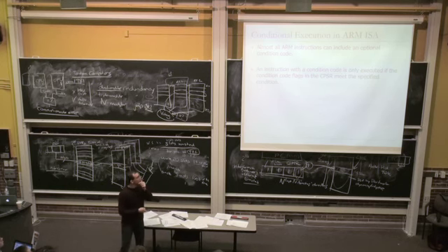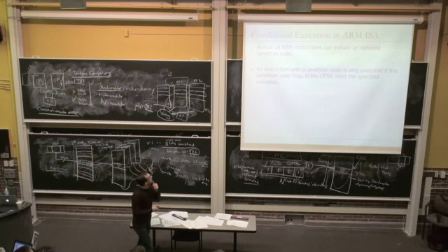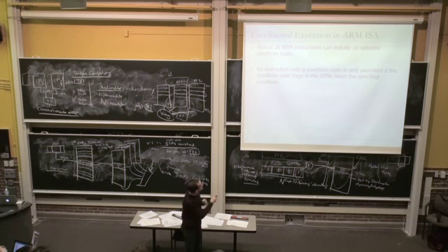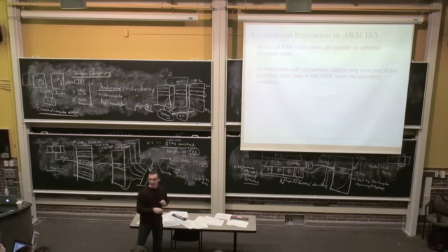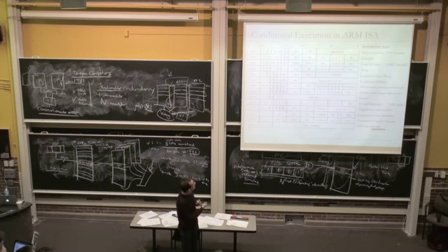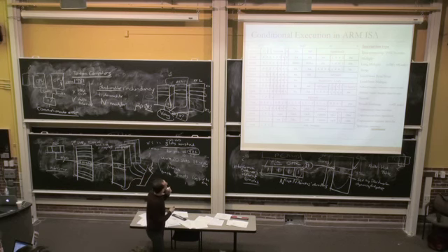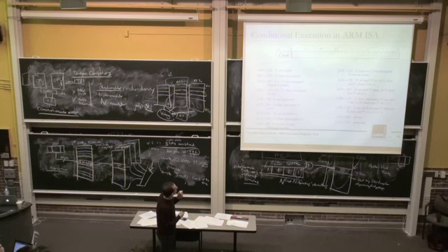Well, looks like many of you know the conditional execution in the ARM ISA. Almost all ARM instructions can include an optional condition code, and an instruction with a condition code is only executed if the condition code flags in the processor status register meet the specified condition. These are some slides I stole from ARM. If you look at the ARM instruction format, for all of the instructions, the top 4 bits are dedicated to the condition code. This specifies when this instruction should take effect, which is essentially a predicate. So you can have 16 conditions, and these are the conditions.